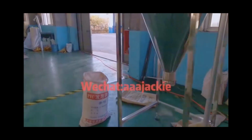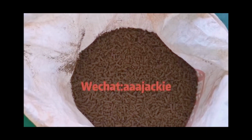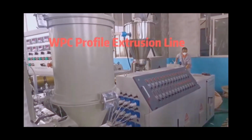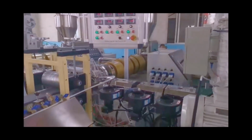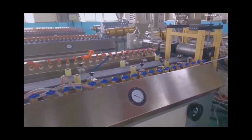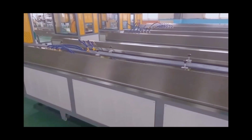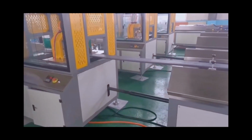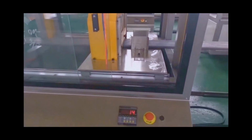So you can see that the polymer is becoming brown, of course, because of the wood powder. This color comes from the presence of lignin, because pure cellulose is white, but when lignin is present, it's darker. And it can also result from some degradation. Because in this case, I think PET was used, so it can be extruded at quite high temperature, meaning that some degradation can be observed.